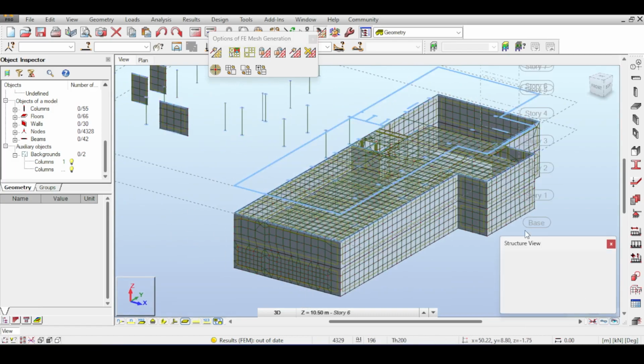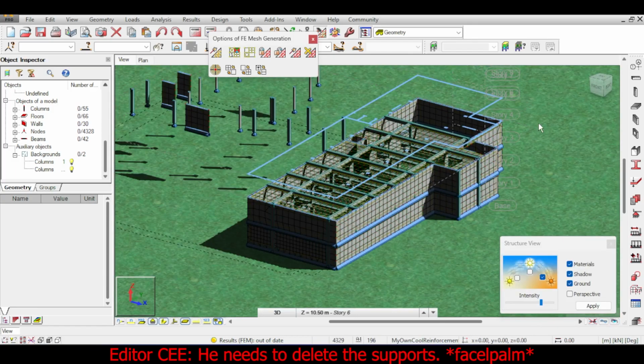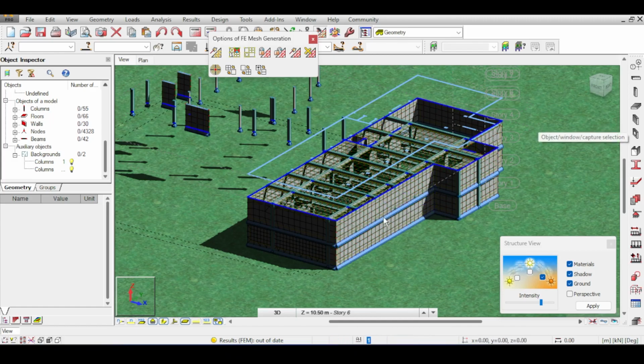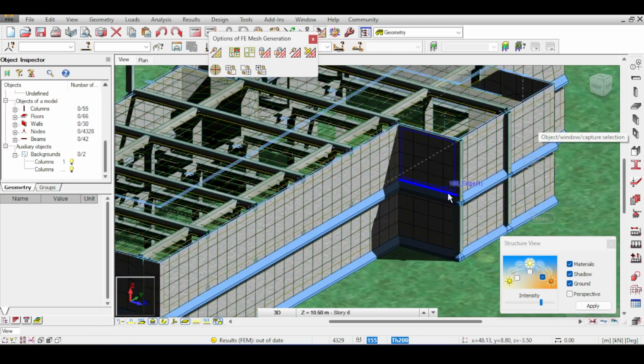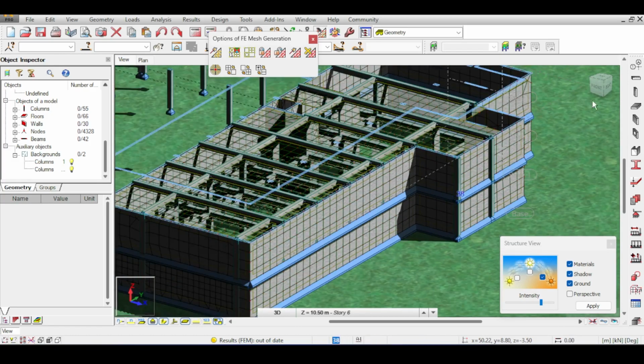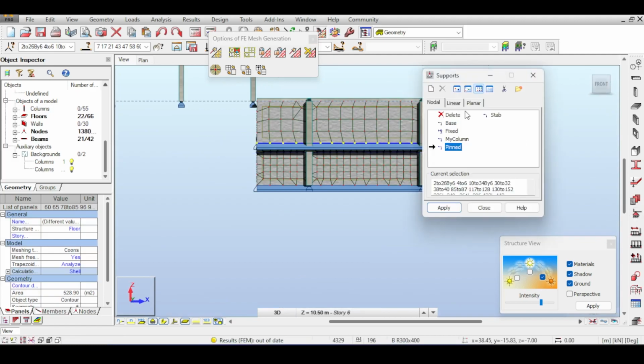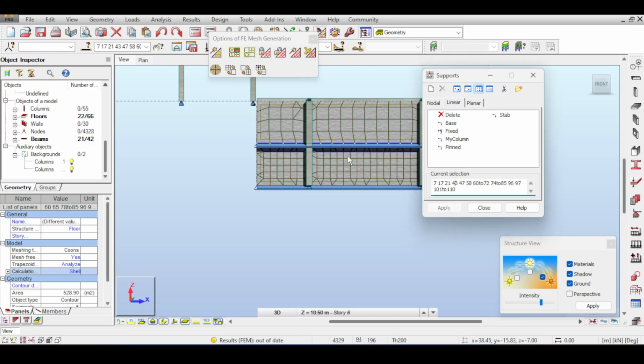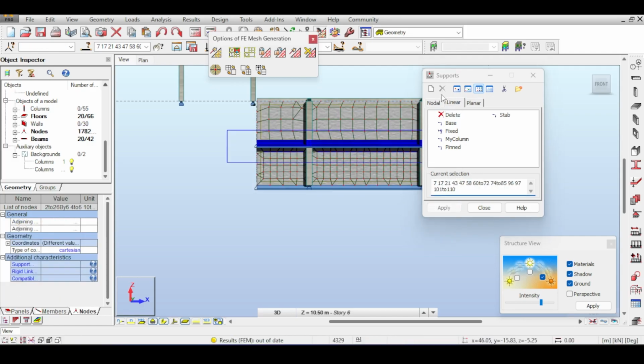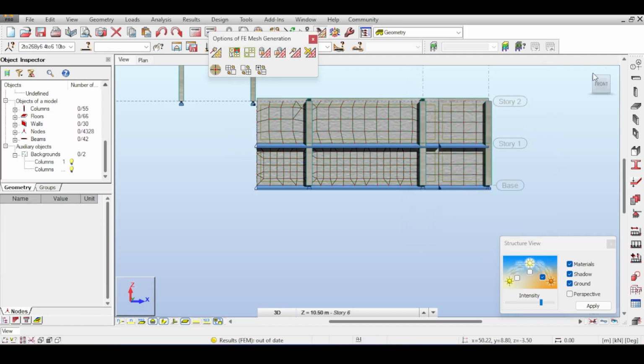I don't see a problem so far, so I think that's a good job. So, yeah. With that, I think we have finished modeling the basement, with exception. Oh wait, I thought I didn't copy those supports. But that's easy. I'll just go here very quickly, select those all, go to support, add a delete to the nodes, and add a delete to those things. Can I do that? Let me just try. It doesn't work. Really? I have to do it by hand?